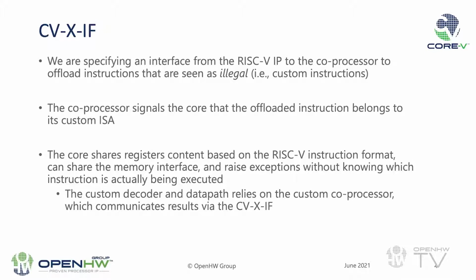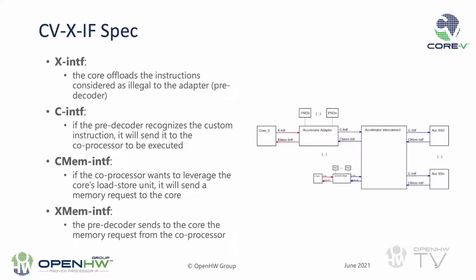On the other side of the interface, we have your coprocessor that is decoding your custom extension, signaling the core, hey, this instruction is mine, it's not just illegal, and it will then execute the custom extensions and report back to the core the results so that they are stored in the register file.